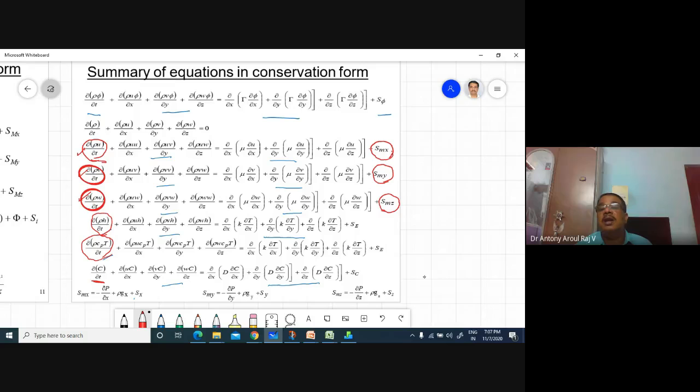For example, if you are asked to model an air conditioner inside the room, you know the fan is a momentum source. So you will have an evaporator, or indoor unit, working inside the room, and inside that the fan will be there. If you want to do the simulation as per CFD, then what should you do? You have to model the fan, mesh the fan, and then you have to write the setup. But if you are an expert in CFD, you know that this process is very difficult: modeling the fan blades, multiple fan blades, giving the boundary condition and running.